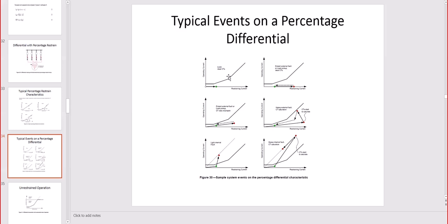And again, the operating current is the difference, in minus out, and the restraint is typically an average summation of the CTs. So it is the sum in absolute value, not vectorial, of those currents over the number of feeders, inputs, or CTs.